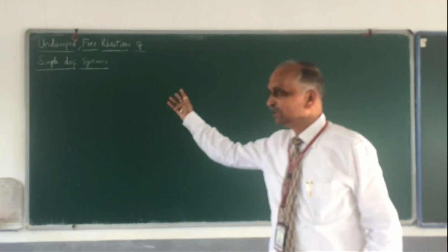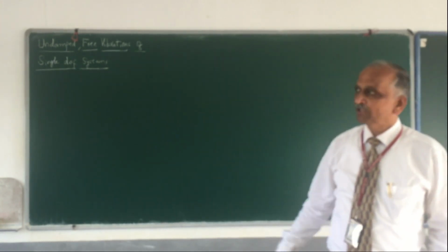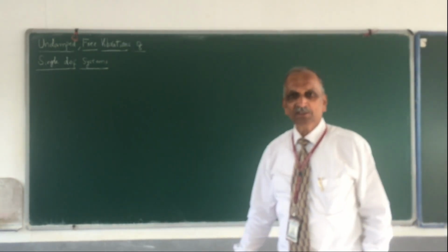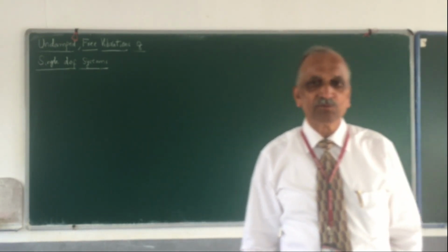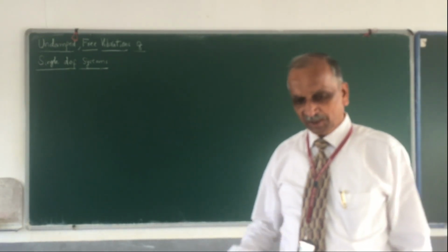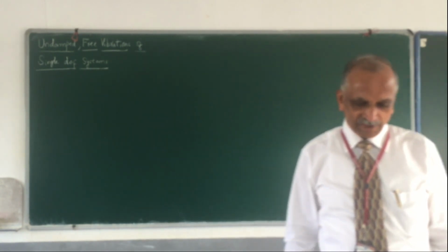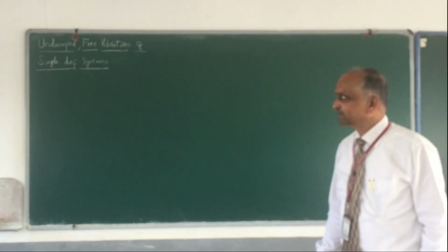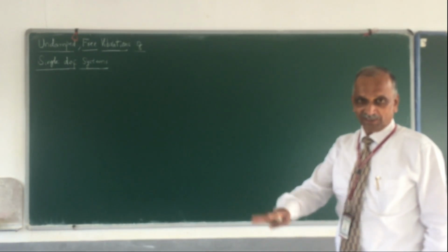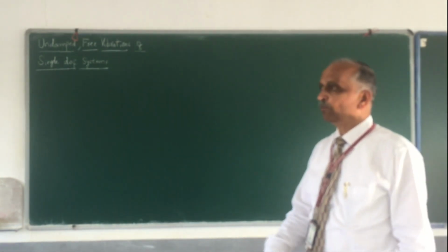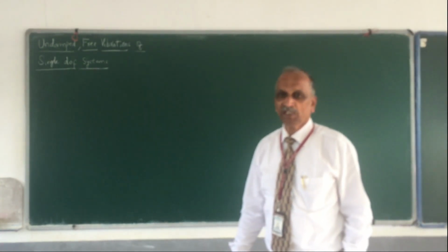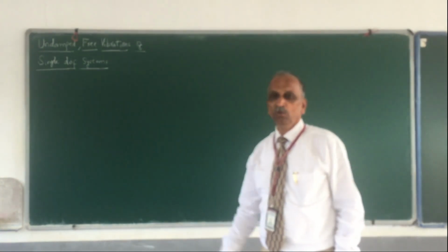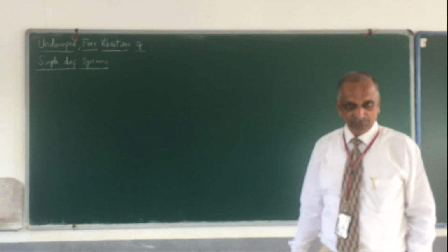The system is going to be a spring mass system, and what we are going to understand or determine is what is called the natural frequency of the system. I also explained why we find out the natural frequency of the system. Mainly, again to repeat it, to avoid resonance. We want to avoid resonance. For that purpose, I need to know what is the natural frequency of the system.